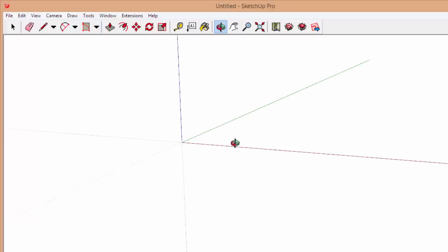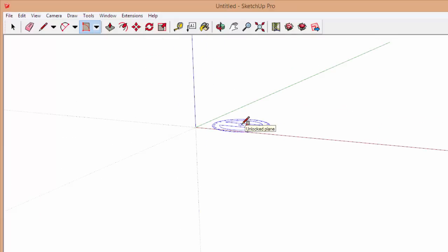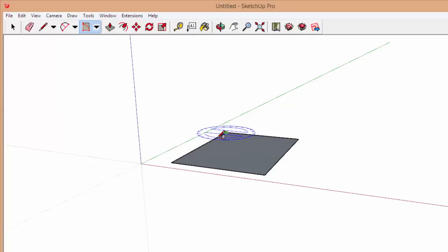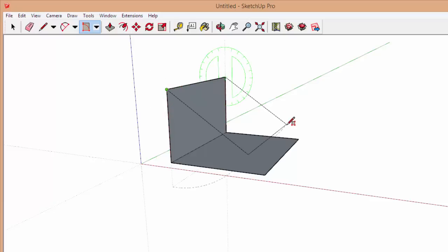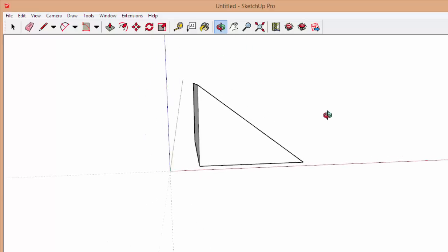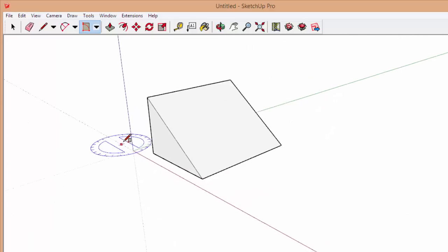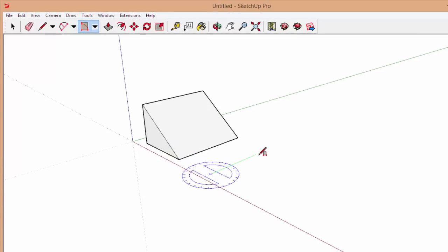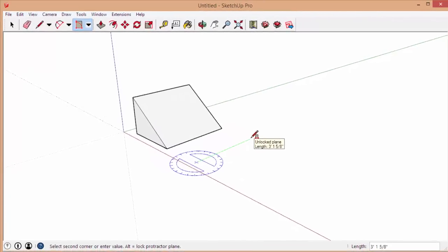For now, let's just use the rotated rectangle tool as a 3-point rectangle. So just click 3 points to define the rectangle. Just ignore the protractor helper that you see on the screen for now, and just practice clicking 3 points to define the rectangle. And you can create a shape like this. Next, let's take a look at some of the power behind the rotated rectangle tool.